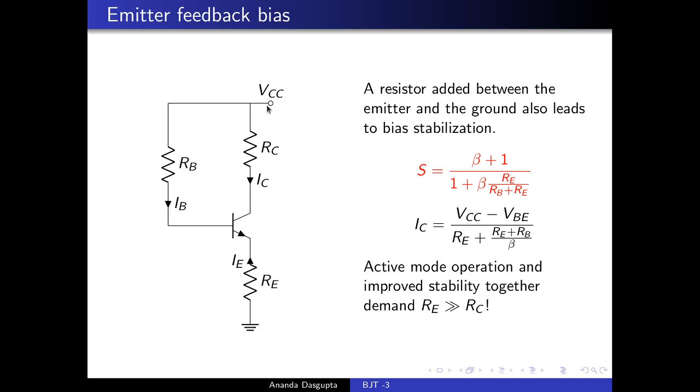So what will happen is your circuit will show significant distortion in the amplification of the input to the output, because the output will clip, because it will not be able to go beyond VCC. So that's one problem. The linear region of operation of this circuit is rather strongly limited.